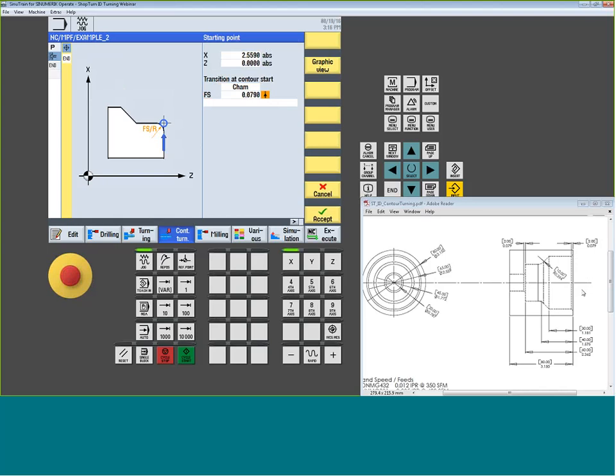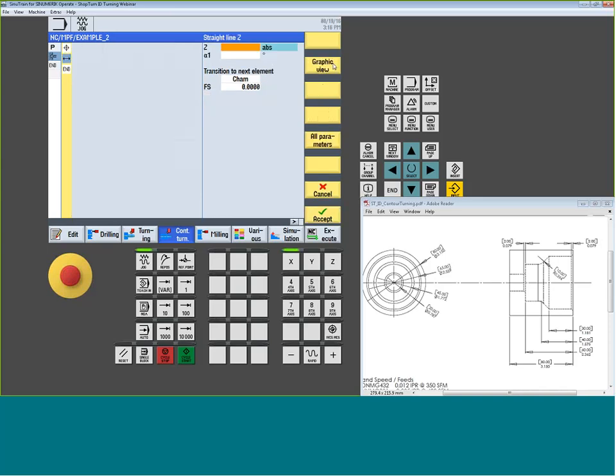This has to align with the direction of motion, so the direction that the chamfer is pointing in. If you get this wrong, you're either not going to get any chamfer at all, or it's going to go the wrong way. So don't be afraid. Just pick one if you don't understand it. But generally, it's going to be your point of direction, kind of pointing to the path I would take. If this was an OD part, I would have used the inverse. But since I'm pointing down, that's the direction I'm going to be moving for my cuts for X. I pointed down. Okay, we give our first position.